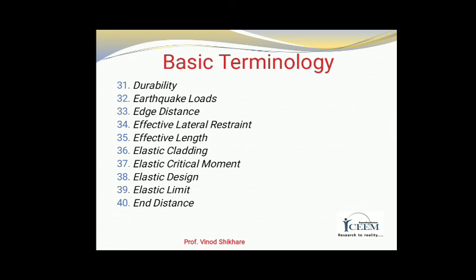Distance from the center of a fastener hole to the nearest edge of an element measured perpendicular to the direction of load transfer. Next is effective lateral restraint. Restraint that produces sufficient resistance to prevent deformation in the lateral direction.